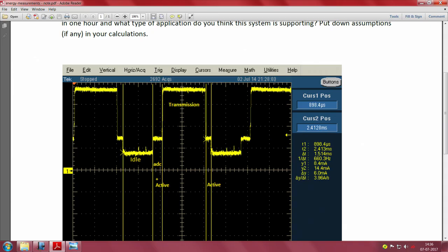It appears that these 3 transmissions that you see back to back need not correspond to Zigbee. It appears that this actually corresponds to Bluetooth low energy, where there are 3 packets being sent out back to back on the 3 broadcast channels of an ultra low power Bluetooth low energy radio. But never mind, I started by saying Zigbee, but I am showing you this picture as a clear indicator that if you do this kind of current capture, you can find out roughly what technology is being used as well.